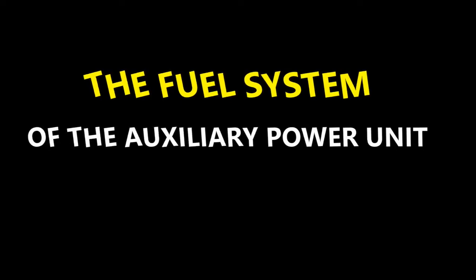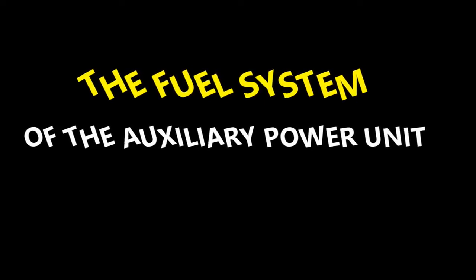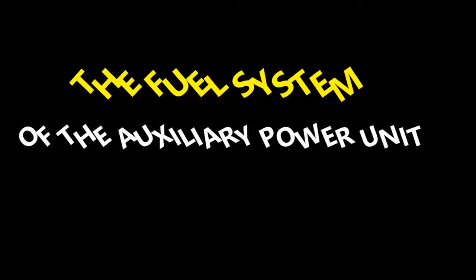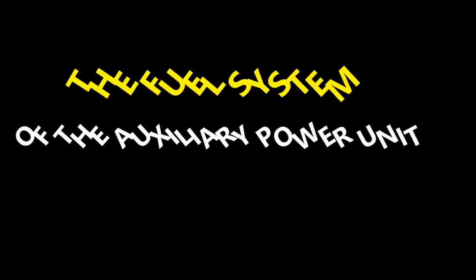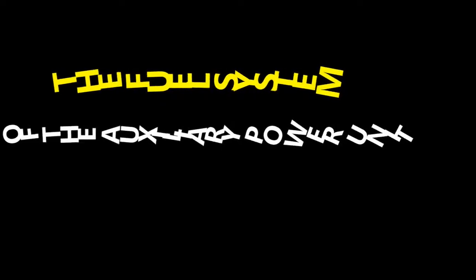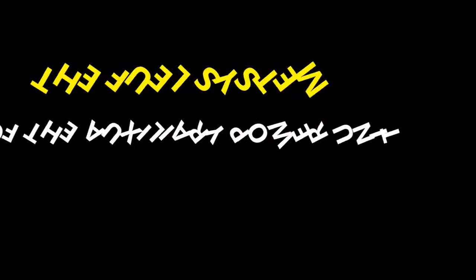And the flow, I mentioned the flow divider. You get your primary and secondary fuel manifold. There are different size fittings for each of the ports on those two, so there's no way you can get them mixed up. A lot of these things are marked so that there's no way you could put it the wrong direction. But the ports are different sizes, so obviously you're going to know if you have put something in the wrong port. But at any rate, I do want to say, please follow the aircraft maintenance manual. All right, so it kind of gives you an idea with that.